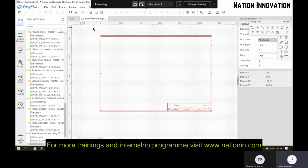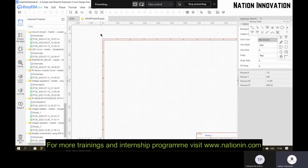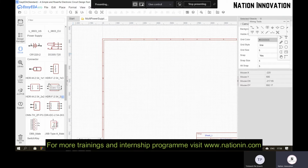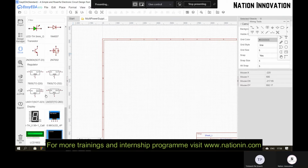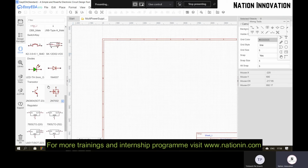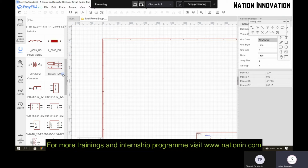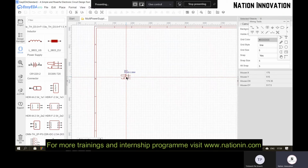To design the DC power supply, we need a DC jack. So to get the DC jack, you need to go for E library. So in that E library, scroll down. So search for the DC jack. This is our DC jack. I'm taking this T20 DC jack and place it.